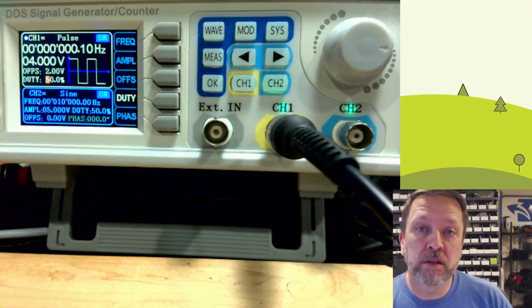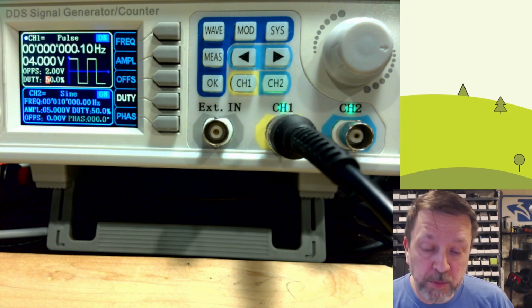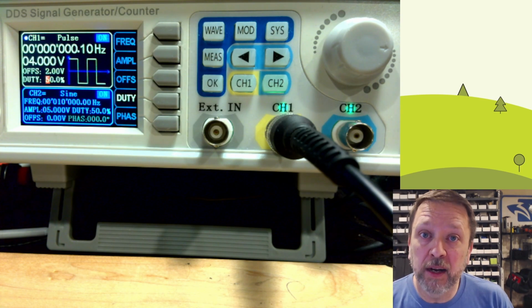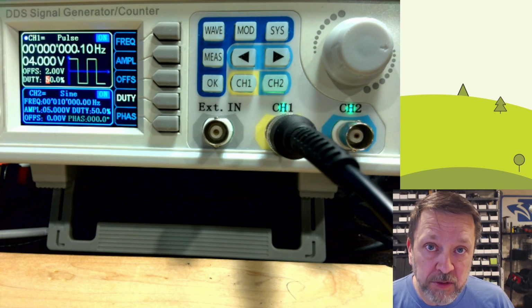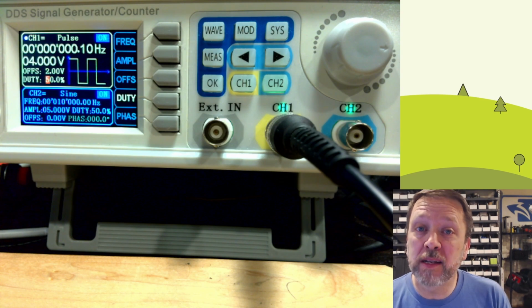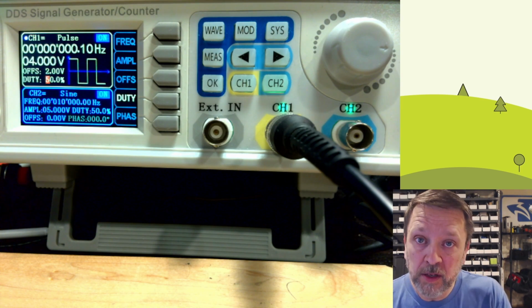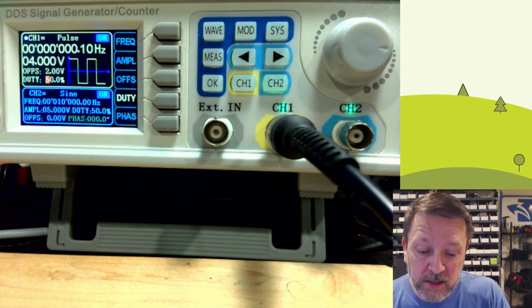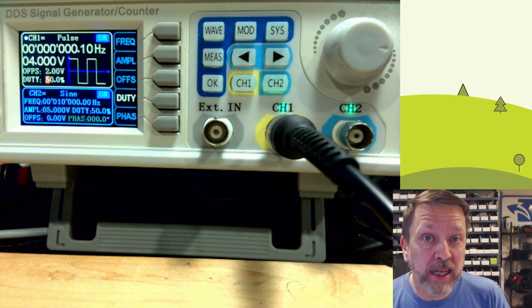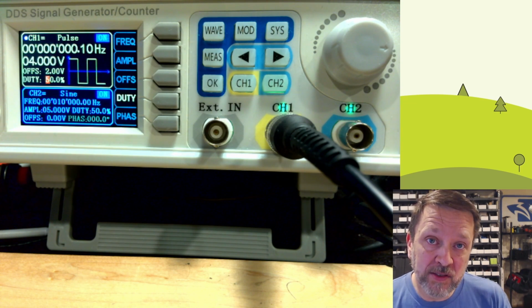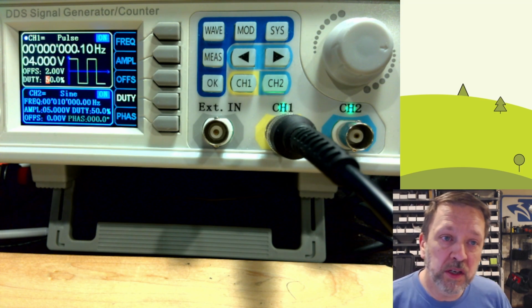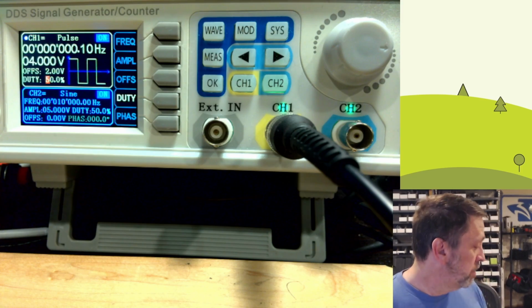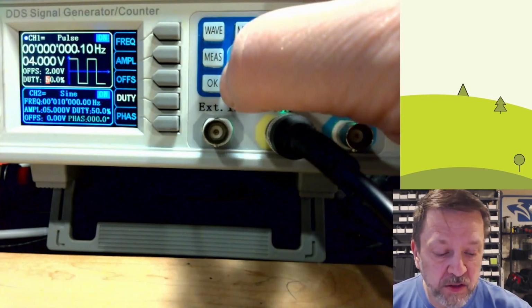Maybe you wanted to test something like a button click where it's a down, up, and then a pause of maybe 10 seconds. Or we want to do a button click every 10 seconds. So click it, wait 10 seconds. Click it, wait 10 seconds. Again, that 10 seconds is our period. We invert that to get frequency. So same frequency, 0.1 hertz. But we would just adjust the duty cycle.